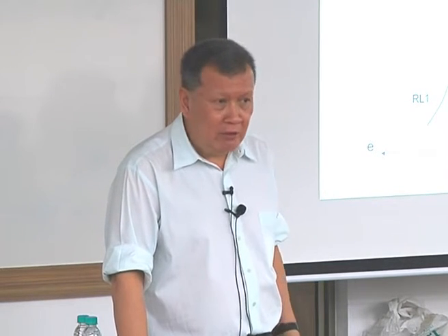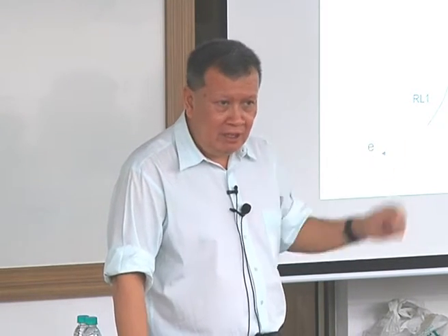I believe Andrew Whittle's MIT model, with E1, E2, E3, and S1, S2 or whatever, tries to describe this particular thing. But for the purpose of our discussion here, I don't think we'll be able to go that far as to explore the differences between the unloading and the reloading line. We will just have to regard it as one and the same.